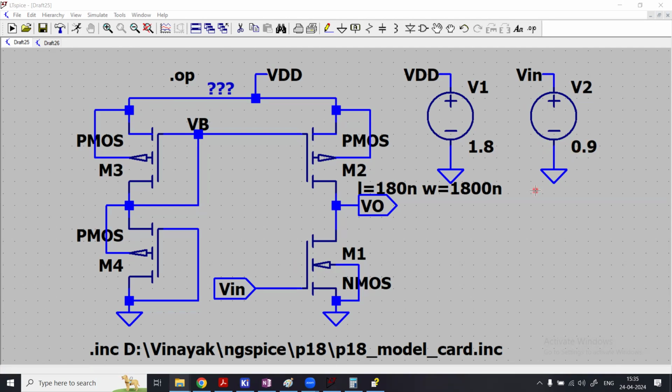So in this case of the transistor, we have got VGS greater than VTH. Let me write that here: VGS greater than VTH. Here also you now have 1.8 volts, and the threshold here is 0.39 volts, and the voltage here will be 0.9, because they are acting as a voltage divider.